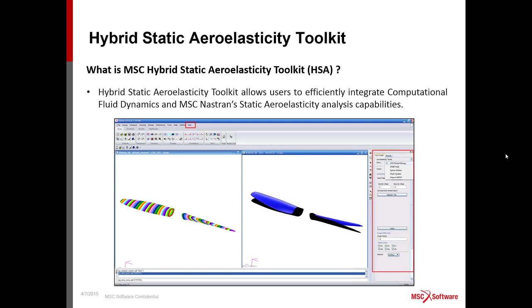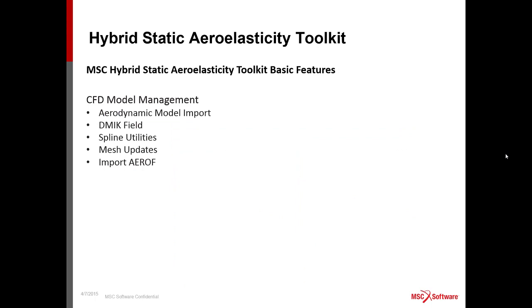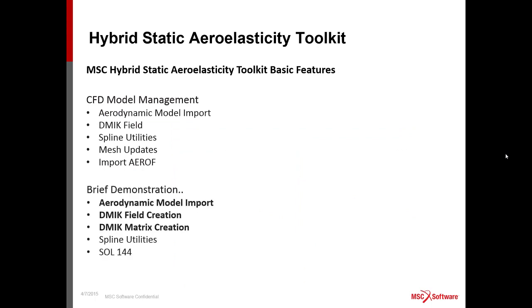And what is the HSA Toolkit? The HSA Toolkit is a graphical user interface in combination with Nastran that allows the user to efficiently integrate computational fluid dynamics and MSC Nastran static aeroelastic capabilities. As you can see, it is an add-on in Patran Flight Loads. You have the HSA button, and this opens a menu in which we developed some main actions in order to manipulate CFD data. I'm going to explain all of these capabilities with a brief demonstration.